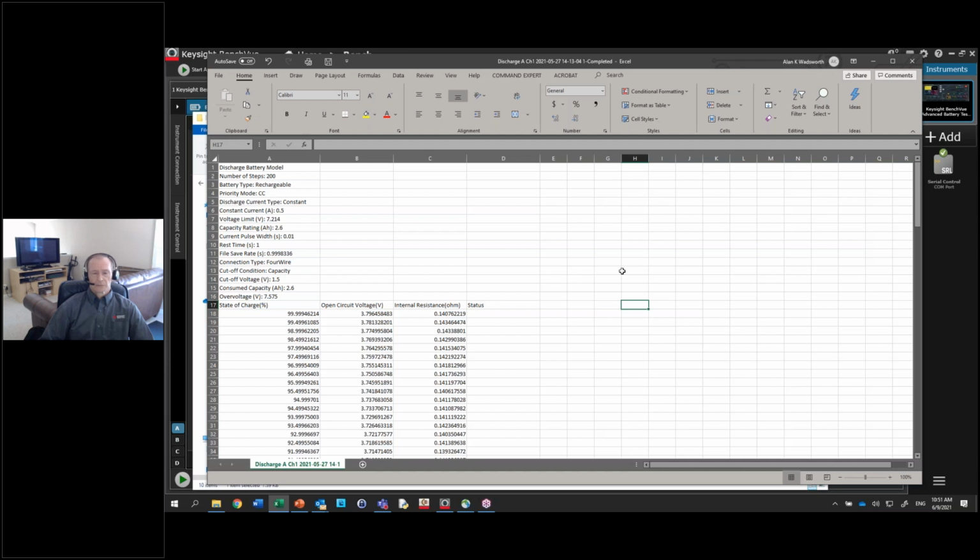Okay, sounds good. The next question is, does the N6705C, for example, include thermocouple input to monitor a thermal safety cutoff? That's a great question. So, our N6705 is basically just a power source. We do have products like our DAQ product line that could be used to measure and monitor temperatures of cells. And the nice thing about that is that our software runs on the BenchVue platform.